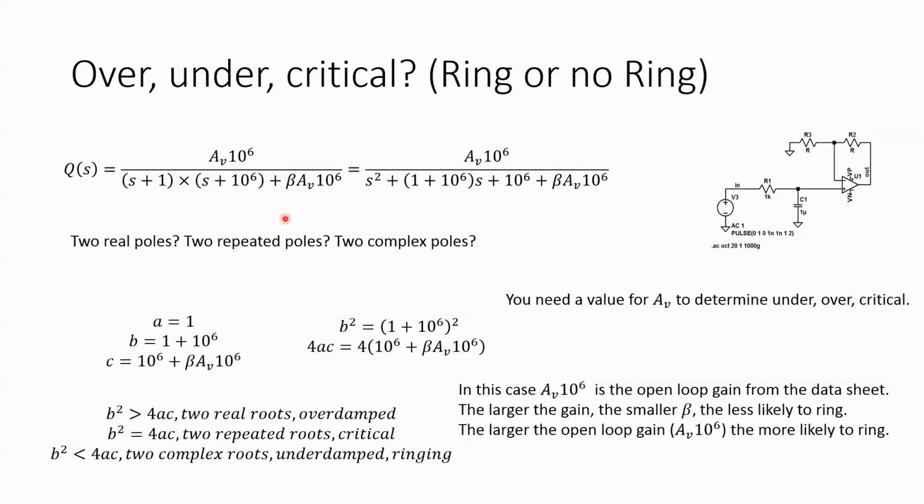Coming up with these poles, you can't really get that from the data sheet. Not really. I looked at LTspice and just started doing Bode plots and basically identifying the system that they had in there. But here's the thing.